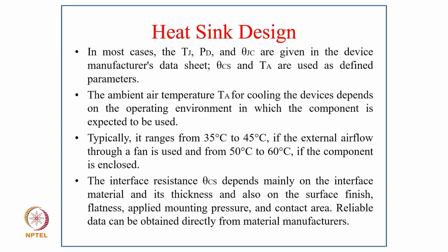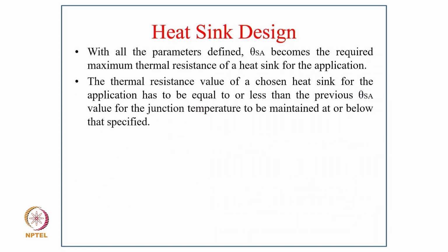And the reliability data can be obtained directly from the material manufacturer. So with all the parameters defined, theta Sa becomes the required maximum thermal resistance of the heat sink for the application, and the thermal resistance value of the chosen heat sink for the application must be equal to or less than the previous theta Sa value for the junction temperature to be maintained at or below the specified value.